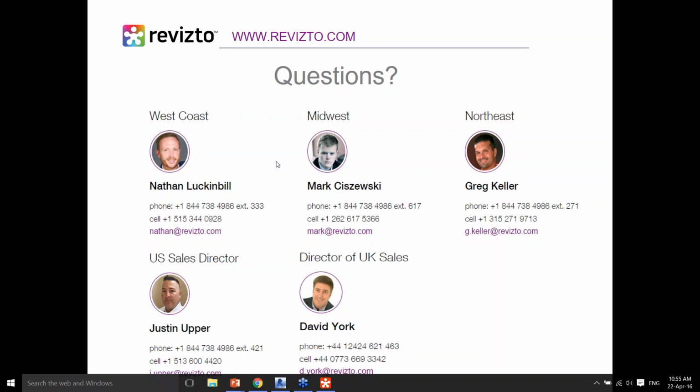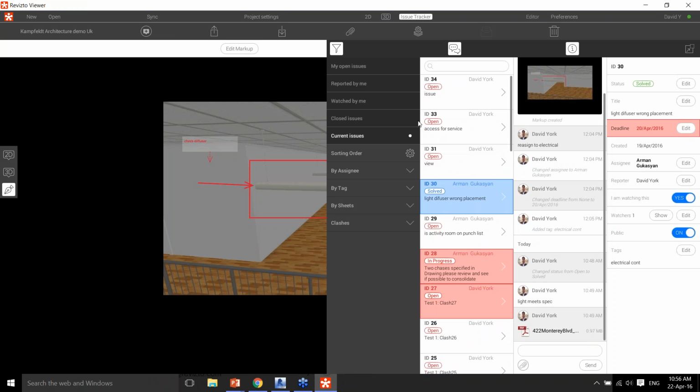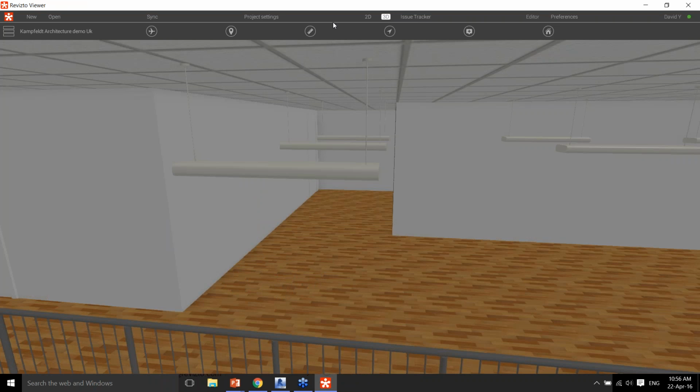We have a question from Javier. Is there a tool to find and isolate objects? Maybe search by sub-objects? Yes, there is. Javier, I'm just going to switch back into my Revizto viewer real quick for you, just to highlight this. If I go to my 3D, you can see on the left-hand side of the Revizto, this is both in 3.7 and 4.0, you have three little bars. If you go into those three little bars,